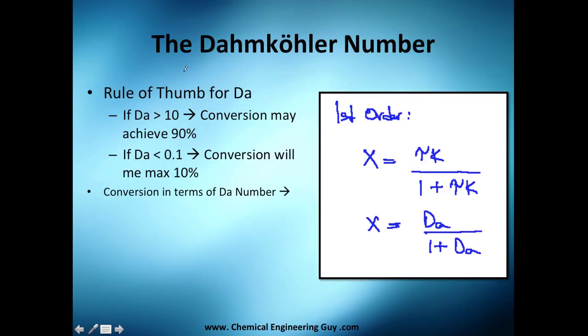I told you before that we could know how well an equation or a reactor will perform. Let me introduce you to this rule of thumb of the Damköhler number. And I say rule of thumb because it's not a super rule or a perfect heuristic, or something that always happens. It is just a rule of thumb in general. You will need to do your analysis, but for very quick estimations, it's okay. If you're talking with your boss and of course you don't want to take out your Aspen computer or your programs in Excel or look at all the data, you just ask, what's the Damköhler number? You find it, and yes, it's bigger than 50% conversion, or at least more or less. Sure, if you're going to design it, you're not going to just use this rule of thumb, but for the moment, it's okay.